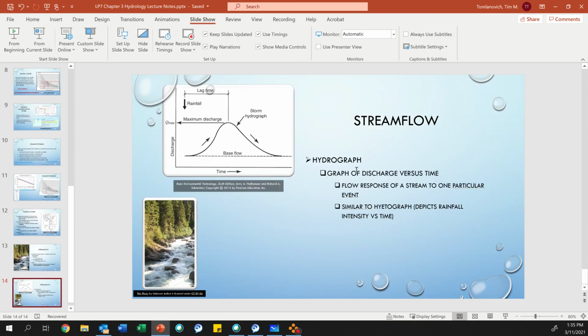Okay. So stream flow is similar to the hydrograph, and basically we call it a hydrograph. Basically discharge, Q, this is what we need to find, Q versus time. So here's that base flow term again. This stream has a base flow. So when it rains, once the water hits the river, it takes time for the water to build up and then to dissipate. They go through the system from point A to point B. So basically, this is what we need to figure out.